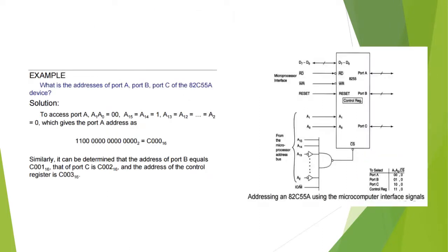Also last class we discussed how to find the address. It depends on three signals. One is the chip select signal. The chip select signal must be low. Wherever the signal is coming from, if it has a bubble, or no bubble but a bar, that means it is an active low signal. It is active when it gets a low signal here. That is the idea of it.